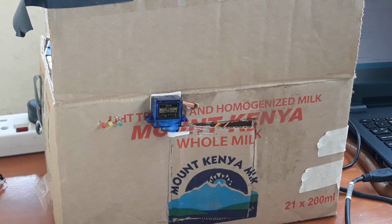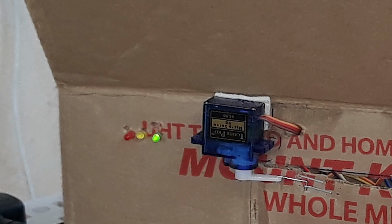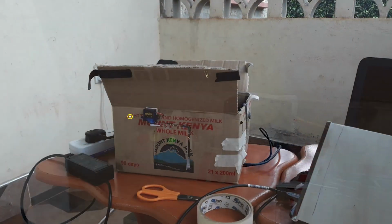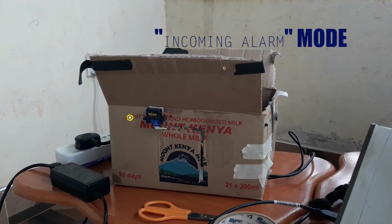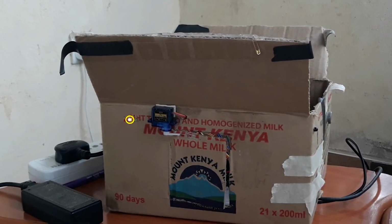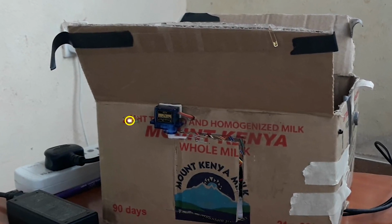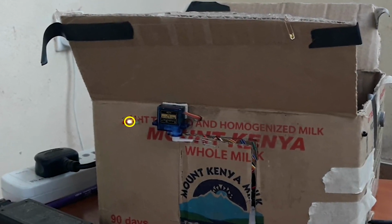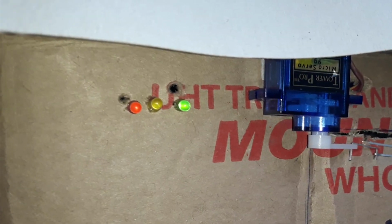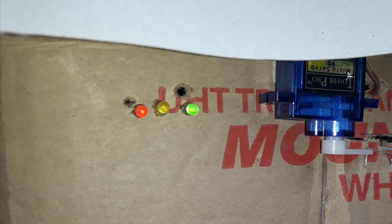The green indicator means the system is okay, meaning all the readings from the sensors are below the set threshold. Yellow indicator means that the system is in an incoming alarm mode, meaning there is an incoming alarm. The user has an opportunity to cancel the incoming alarm if there is no fire incident. We'll explain more about this. Red indicator indicates that there is a fire incident and the alarm is on.